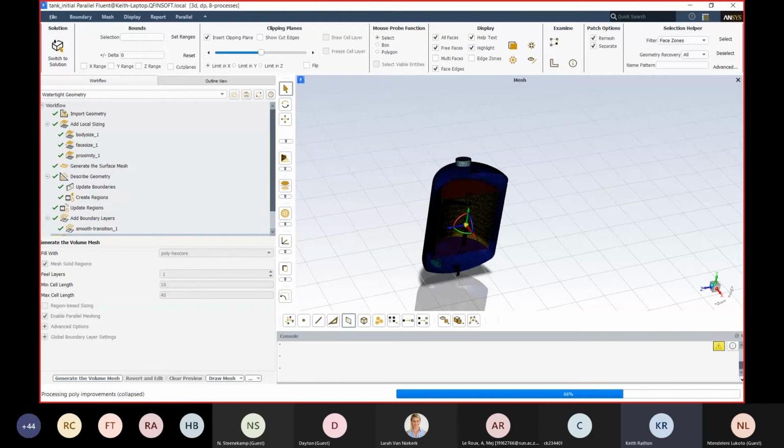The one nice thing is that Fluent and Fluent Mesher have the scripting, and now Fluent has what they call expressions, where you can get away with a lot of your calculations and manipulation through the expressions rather than using scripting.